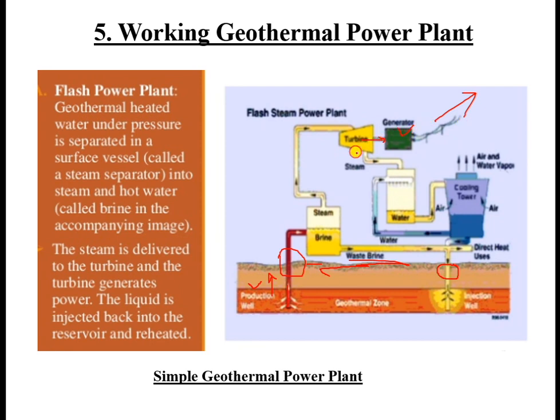Again, whenever the steam comes out through this turbine after doing its work on the turbine blades, it will have a lower pressure as well as a somewhat lower temperature compared to the earlier location, and then it is passed out through this condenser. Again its condensation takes place, and the condensate which is formed here can be extracted, passing through the cooling tower.